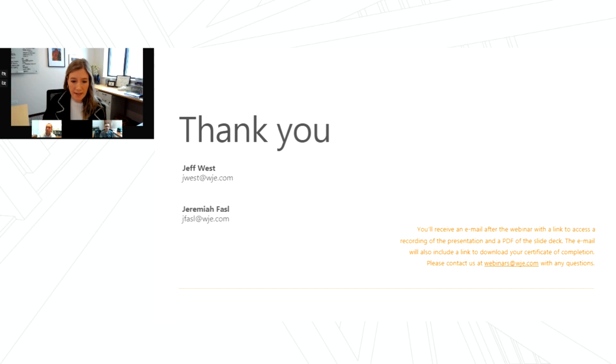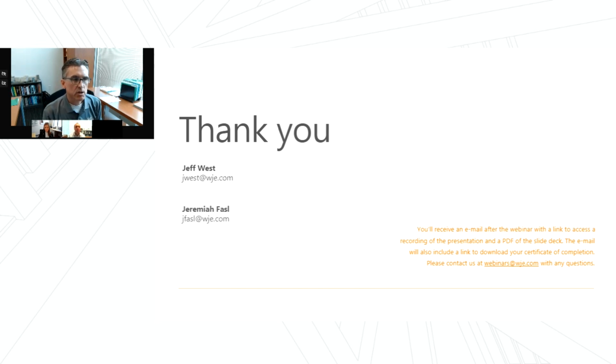Why have you decided a minimum 10% for the delamination survey and hammer sounding? I can take that one. So that is always a judgment call. There are some guidelines in some of the ASCE documents, particularly I believe in the ASCE 101 document for underwater inspections, that talks about a level 2 survey involving at least 10%.